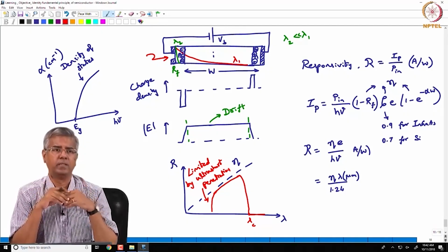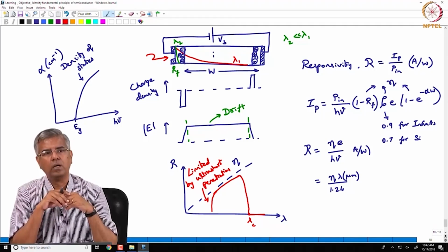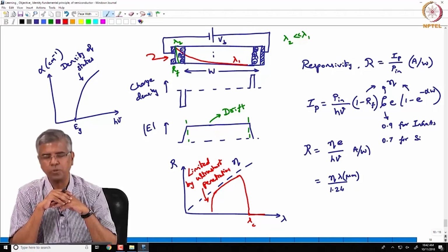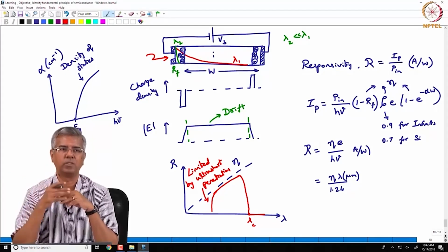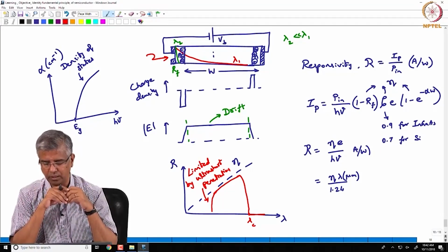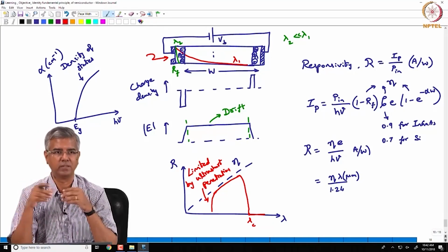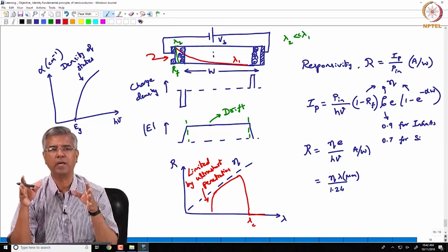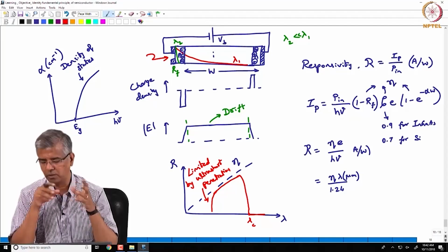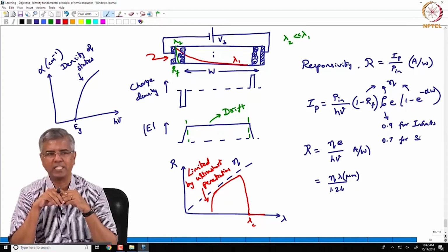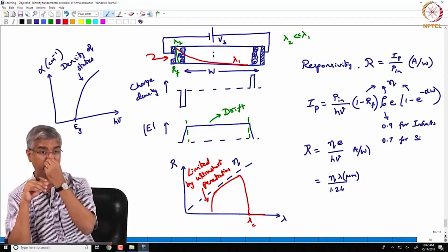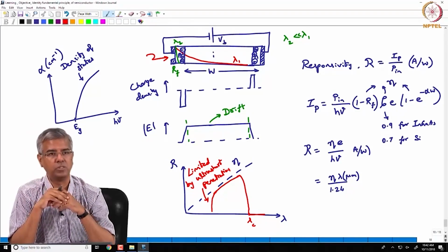Part of it could be. Yeah, we're just looking at the first level thing, but if you leave light over there, some of those photons can come back. But you typically design your photodiode for that longest wavelength of operation. So at the longest wavelength, it should be absorbed completely. So then you basically try to maximize that term, to 1. So e power minus alpha w, that fraction is going to be very close to 0.